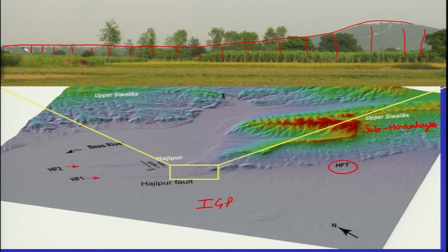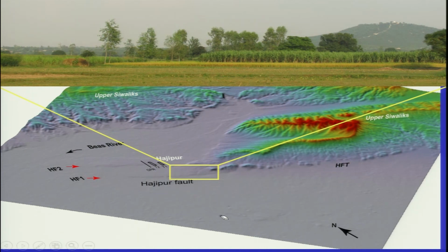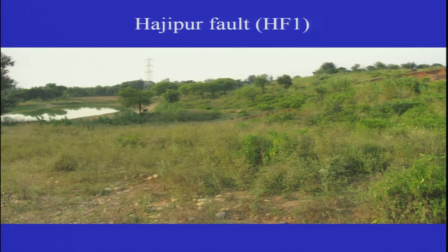So we can pick up this deformation using different ways or techniques which are available, and it can be easily used. Either you are using high resolution satellite photos, or you are using aerial survey data, or you are using the digital elevation model and draping the images on the digital elevation model. So again, the next step will be that you identify the fault scarps and you select the trench site. Okay. So we selected the trench site over here in this portion.